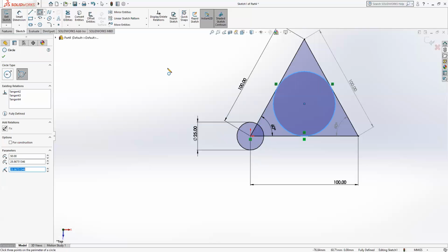Sometimes this is handy if you're sketching things up and you want to draw a circle inside a perimeter, inside a triangle, but also inside of a square, things like that. Instead of trying to find the exact center of that triangle and then drawing your line out and having it meet the edge, which you could do, because you could just draw a center point from here and bring it over, and as soon as it touched this line, it would give you that circle. But this lets you do that without going into that extra step of finding the center point of your triangle. So everybody follow along with that? So far, so good. Okay.